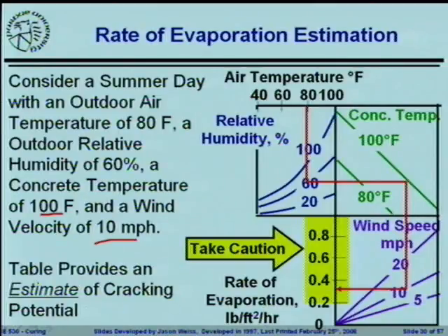So you would enter this graph, and this red line doesn't appear on the nomograph, and you'll actually find that the nomograph doesn't appear in the beautiful Technicolors that I've reproduced it here. But you would come to the graph, you would enter at the top of the graph up here with the air temperature. You would drop down until you hit the relative humidity of the air, which again was 60% relative humidity.